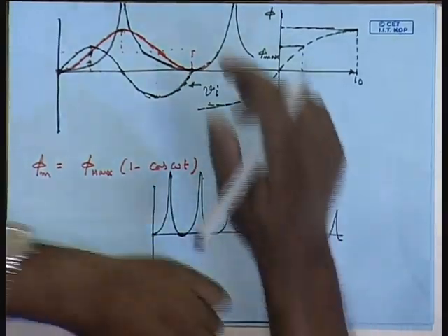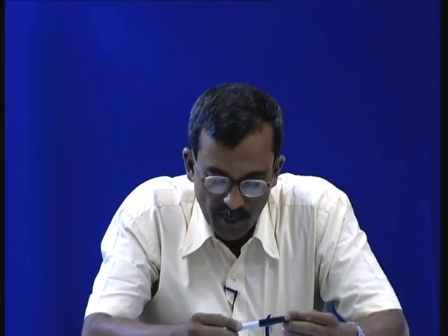So, depending on when the transformer is switched on, it is possible that there will be a magnetic inrush in a single phase transformer, due to which the no load current of the transformer can rise to dangerously high levels for the initial few cycles.